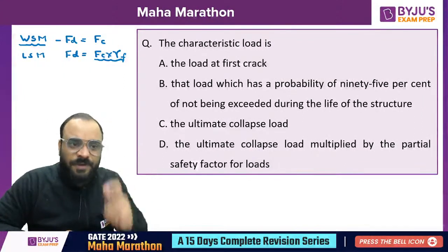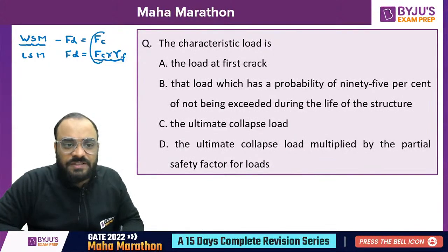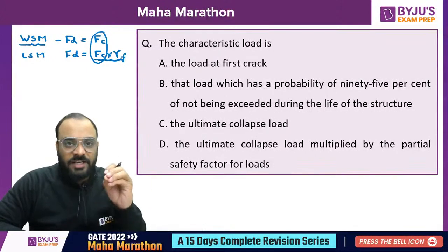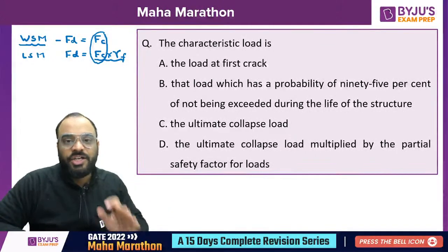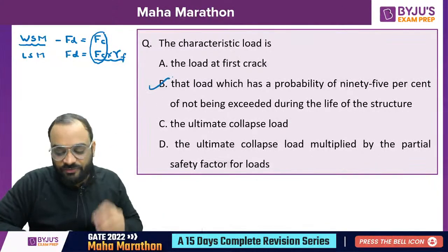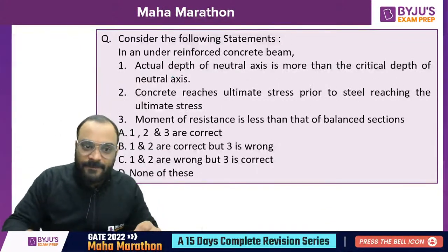And guys, this particular definition of characteristic load is the value of load which has a probability of 95% that it should not be exceeded during the design life of the structure. And that's why, guys, B is the correct answer for this problem. Next question.